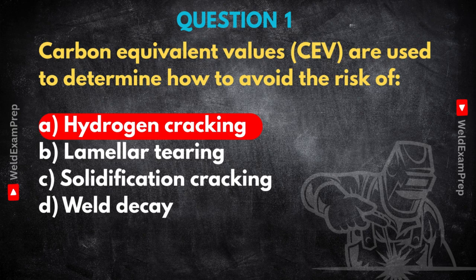Martensite, right? A very hard needle-like structure. Exactly. Super hard but brittle. And it forms when steel cools really quickly from high temperatures, so it's susceptible to failure. Now, add hydrogen into that mix. Hydrogen can come from moisture in your electrodes, your flux, even just the air around you. That hydrogen gets trapped, sort of diffuses into the weld metal, and especially into these new brittle HAZ structures.